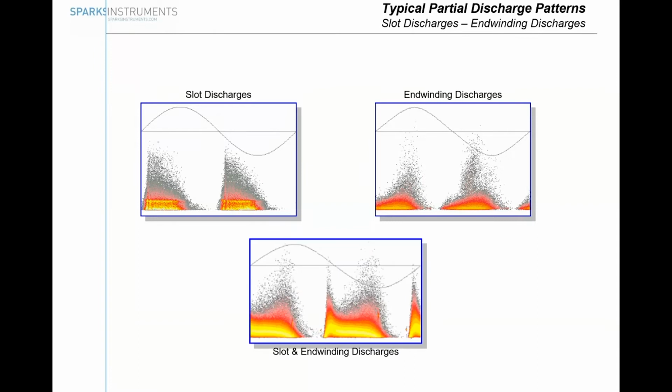With these discharges we can acquire data with the system, and what we do is a statistical analysis of when these discharges happened, how strong they were, and how often. For the statistical analysis, we create a so-called phase-resolved partial discharge pattern, as shown here. Each dot means one discharge. We have the phase angle when they occurred, the magnitude, and the color shows how often. So basically we get a cluster, a color image, and depending on how the defect is, that statistical analysis looks different.